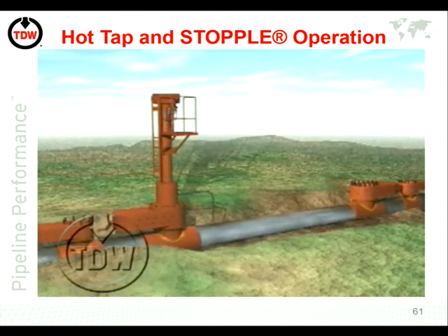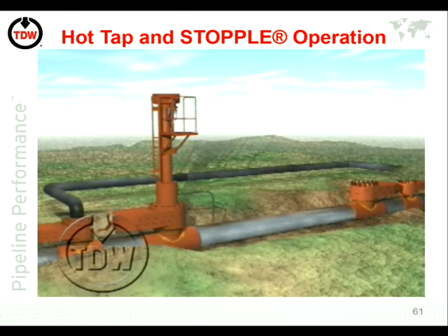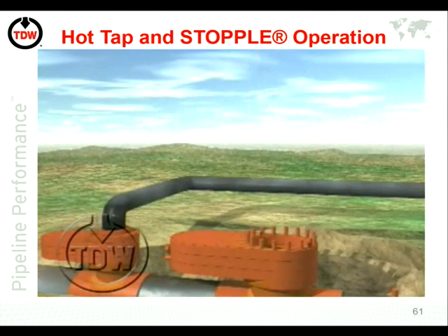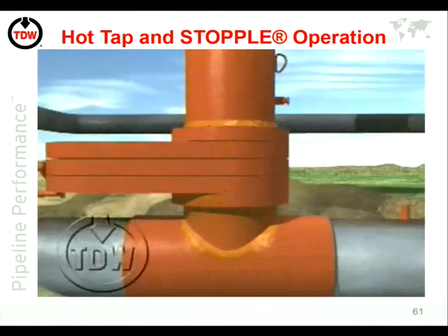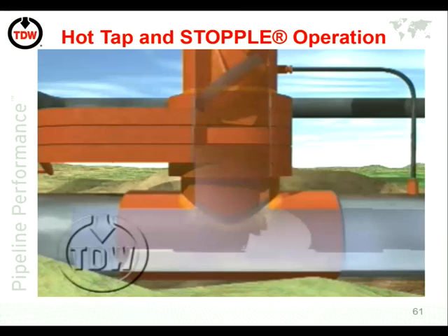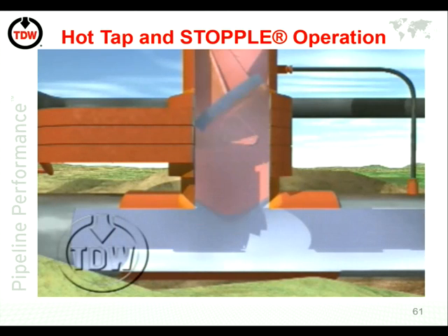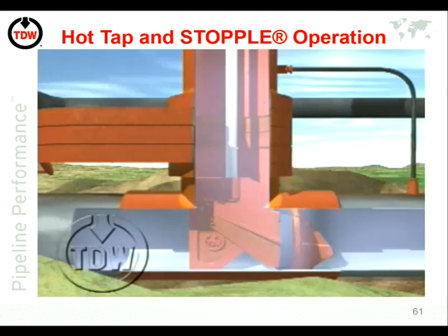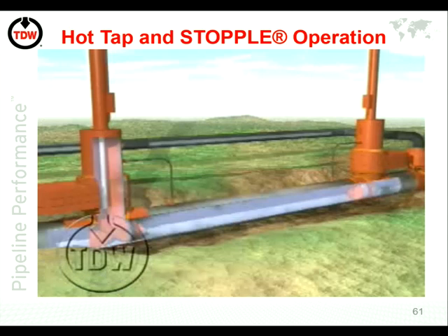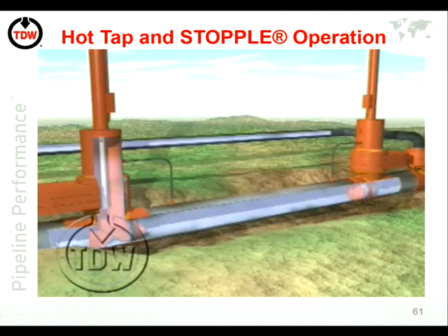At this stage the product will not go through the bypass because it will always go through the point of least resistance, which is typically the pipeline. But to increase that resistance, you put a plug in it. That stops the flow, and that will naturally induce the flow to go around the bypass. So at that stage we've now isolated. We need to release the gas. As I say, this is now captured in